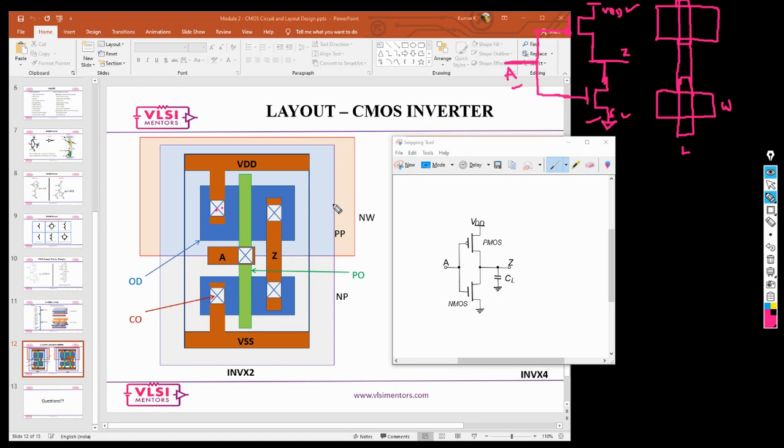Yes. No. Wait. I don't want you to tell me upper part, lower part, and all those things. You need to always use what transistor it is. It is basically a PMOS source that is always connected to VDD. Now, what's your confusion here? No, drain is never connected to VDD. I said only source. So I drew it here clearly. This side is source, and these two are drain. Didn't I? I did.